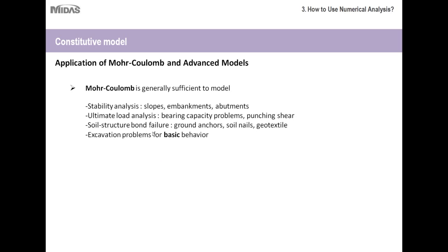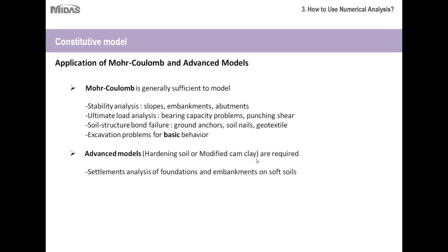So excavation problems for basic behavior. If you have a basic deep excavation, then the Mohr Coulomb model typically will suffice. Now, as far as your advanced models are concerned, the modified Cam clay model is required for the following. Settlement analysis of foundations and embankments on soft soils.